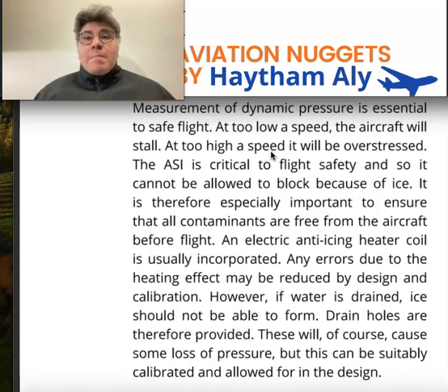Can we measure the dynamic pressure of air? No. What can we measure? Pitot or total pressure? Yes. Static pressure? Yes. So we have the pitot tube and the static port. And pitot minus static equals dynamic. And that's what is happening inside the case of the airspeed indicator.